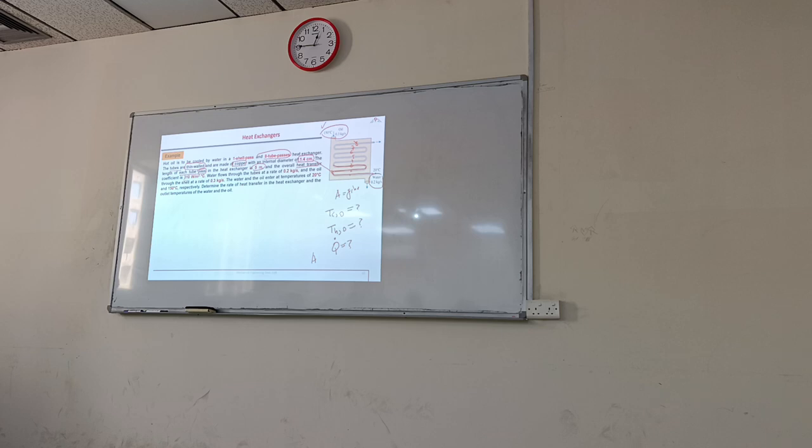The overall heat transfer coefficient U is also given. If it is not given, then you will find it from hi and ho. Here U is given on the basis of inside area. They are approximately equal since the wall is thin; otherwise, the wall dimensions would be given. The flow rates m_c and m_h are given, and the inlet temperatures are given.